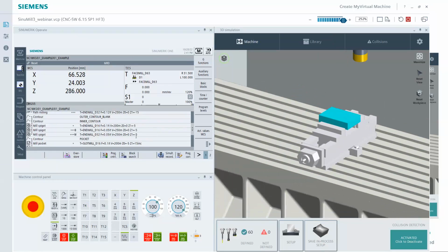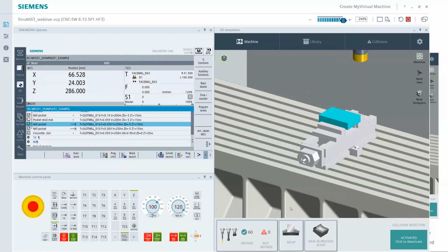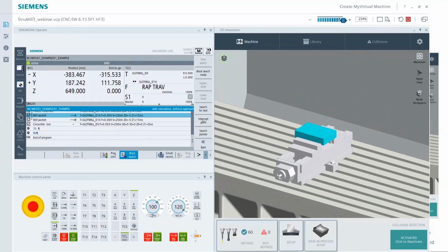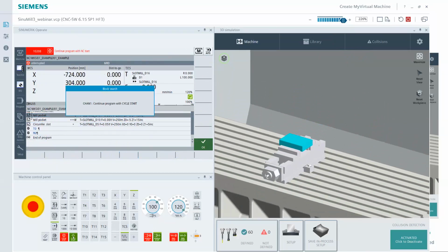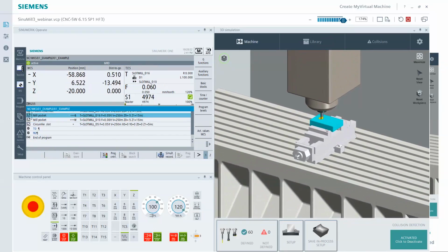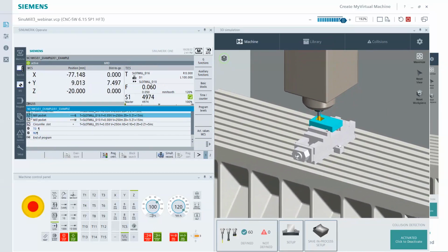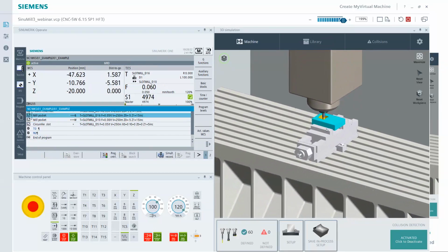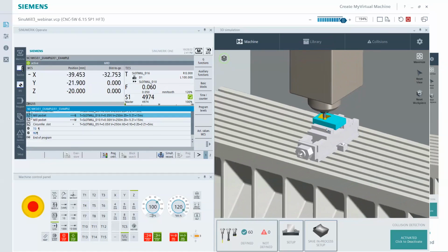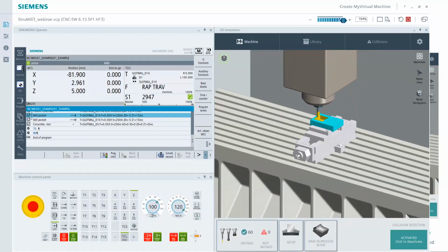If you do a mid-program restart, like let's say I start from this pocket and you hadn't machined all that, it will absolutely work. So we'll do a program start from that point. Grabs a different tool. Yep, double NC cycle start. But of course, it thought it was a collision because the previous operation that had cleared that material is no longer there, or was not there. So just be aware of that. It's not giving us a true representation unless I was literally trying to start the machine in the middle of the program on a part that hasn't had any cutting. But it is a true scenario.